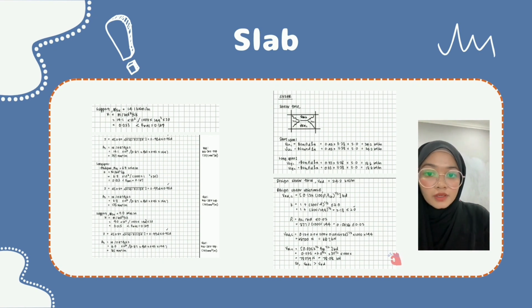And last one for the support, I got the K 0.015 and the Z 0.99D, and also I used the 0.95D. And the last one AS, I got 165 mm square per meter. Again, I used the H12-300 for top, and the AS bar area is 377 mm square per meter.